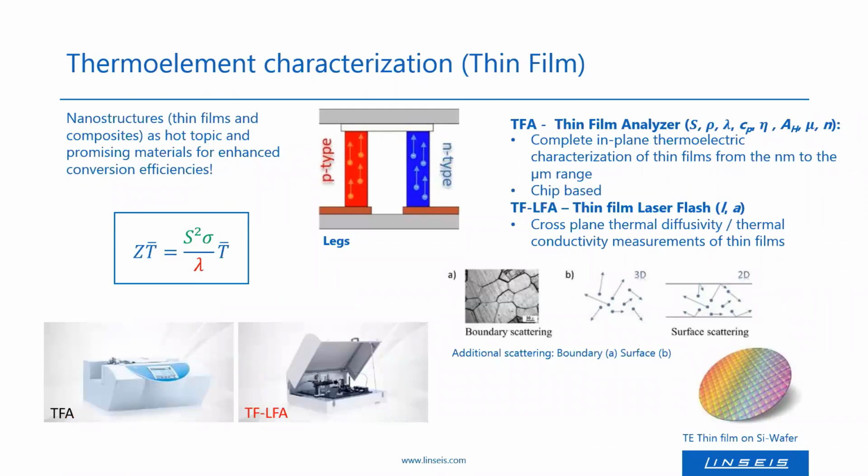And another very important, also recent trend in the field of thermoelectrics is the investigation of nanostructures, as they can possess some very unique features which are advantages for thermoelectric applications. On the one hand, additional charge carriers and phonon scattering within thin films or nanowires can increase the ZT value by suppressing the lattice thermal conductivity or increasing the power factor.